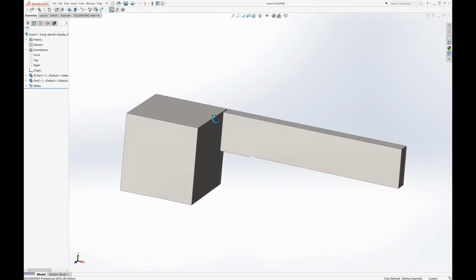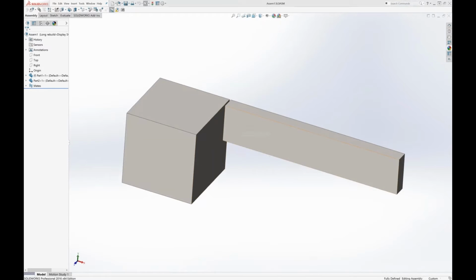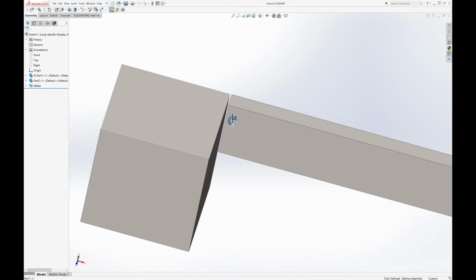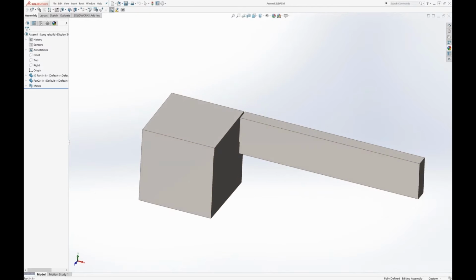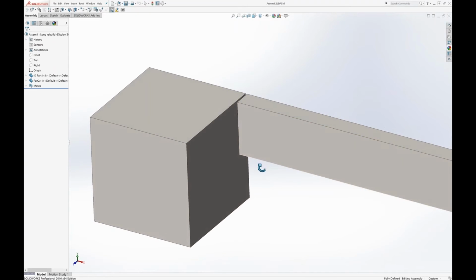So here we need to pretend that this is a manufacturing model, so it's an assembly, and it has two parts, and as would typically happen with a manufacturing model, there's a gap between the two parts. If I was to take this directly into a simulation, then I would need to define materials for both of those bodies, and I would need to define a contact between the two bodies.